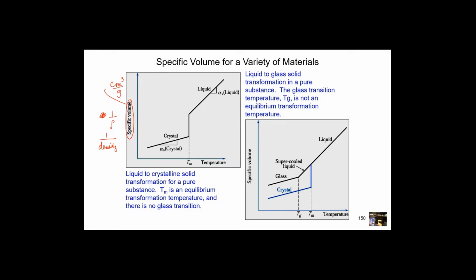Okay, so let's start. The purpose of this particular slide is to compare things that form crystals with things that form glasses, or things that do a little of both, depending. On the left is a typical fluid. Let's just say it's benzene. And up here, because benzene is easy for me to draw, we have all sorts of benzene molecules in different orientations because they're liquid. And they're spinning around and flipping upside down and doing all this stuff. So it's no surprise that comes with that extra volume. As they do all that, there's a little bit of volume in between them. And that volume in between the benzenes is called free volume.